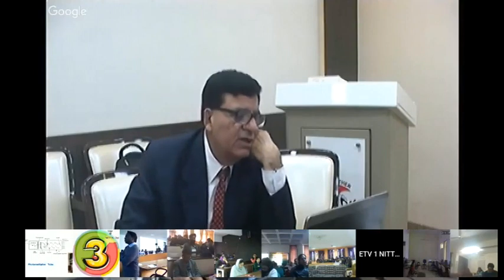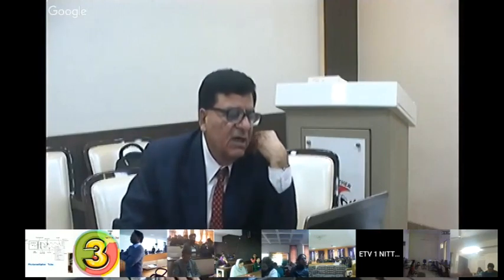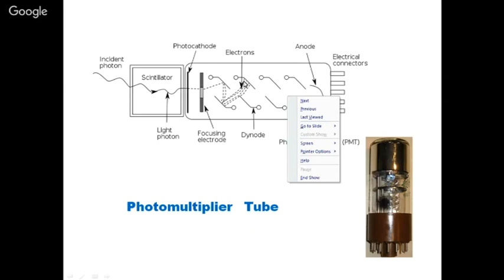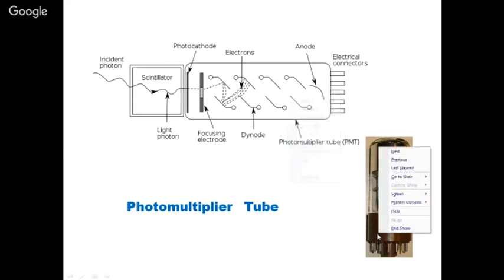These 10, when they go to the next diode, which is at a higher potential, this was in a tube version, valve version, then each of those 10 will generate 10, so it multiplies. So this multiplier system used to work, but as I said, it needed something like 900 volts, because each diode has to have a different voltage of 100 volts each.